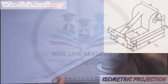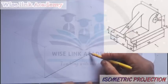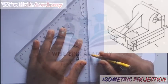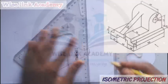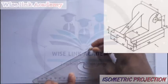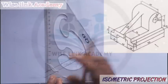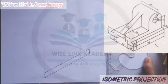That's the first task. Next up, if you observe closely, there's a height of 12. So I measure out 12. This is 0, this is 1, 2. 12 is ticking. I'll tick in mine. Next task, I'll take it inward this way to touch the other edge with a tick line. Then I'll place my T-square vertical this way to close this part up. I have this.